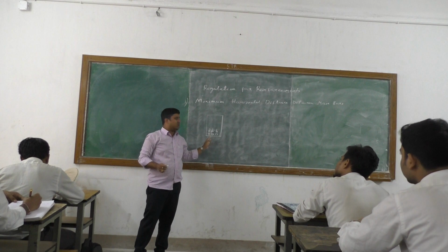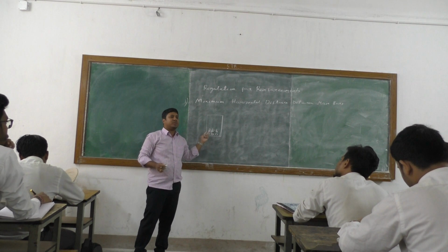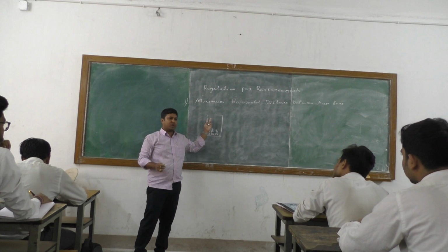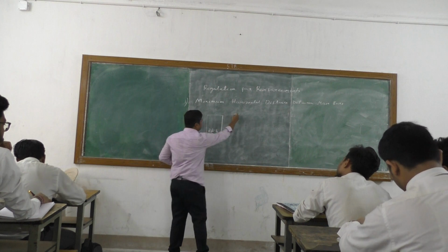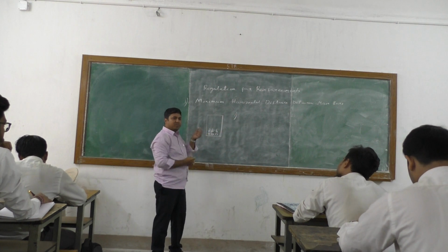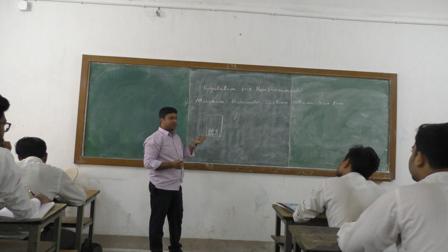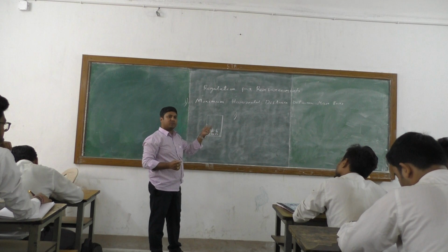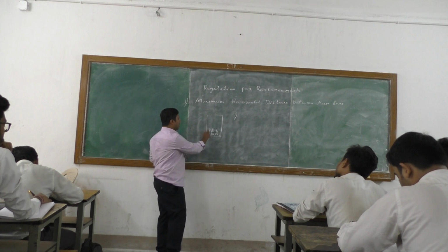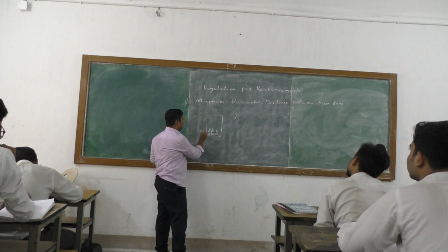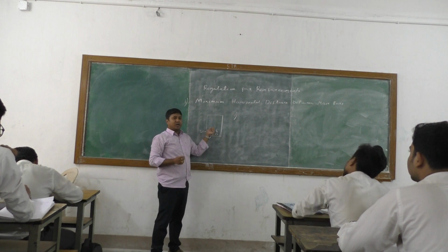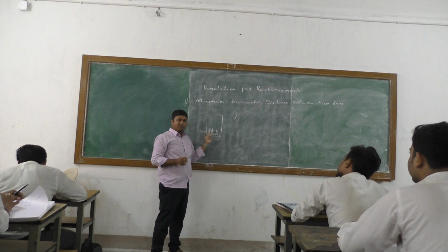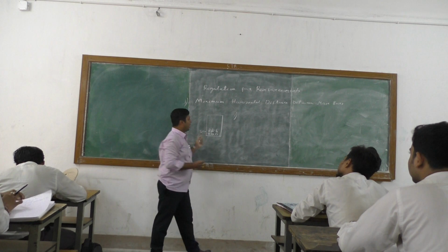For this reason we have provided a minimum clear distance between two primary reinforcements, whether for tension or compression. The first criterion is the diameter of the reinforcement, if all the reinforcements are equal. Suppose all are 20 mm diameter, then the minimum space between the primary reinforcement should be 20 mm.